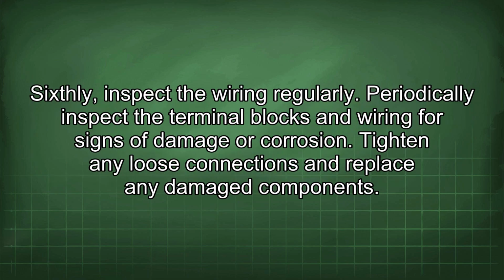Sixthly, inspect the wiring regularly. Periodically inspect the terminal blocks and wiring for signs of damage or corrosion. Tighten any loose connections and replace any damaged components.